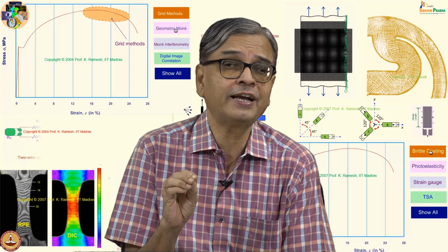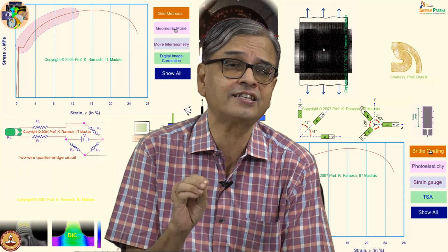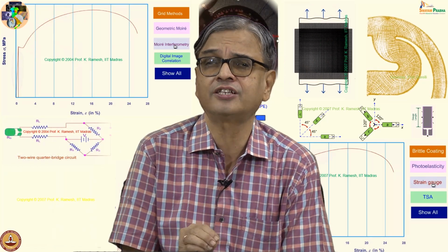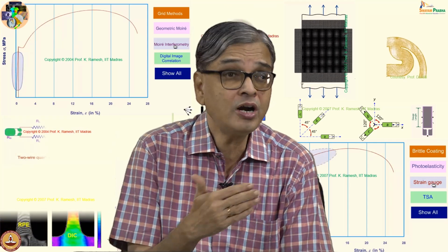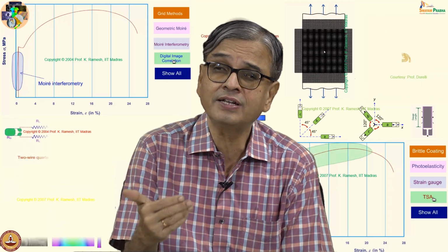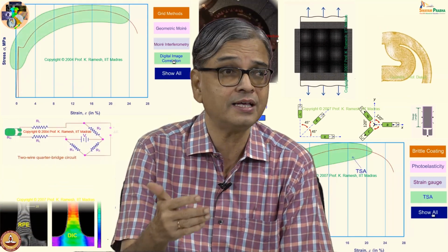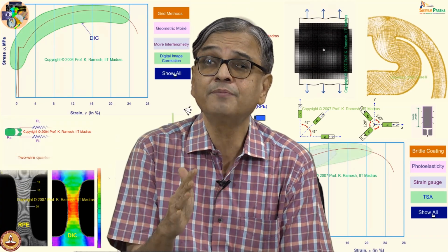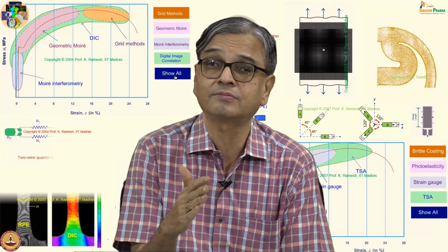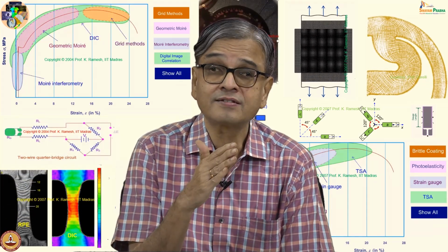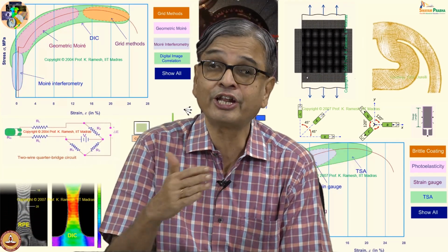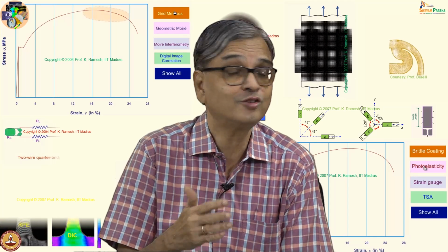But what you have to keep in mind is, technologically strain gauge measurement is very, very sensitive. You need high precision strain gauges. And how do you bond them? How to bond a strain gauge on a given surface on a prototype itself is a very important training a strain gauge measurement specialist has to undergo. And there are certificates given by the British Society of Strain Measurement. You have to renew that certificate every 3 years. So it's not a simple job.